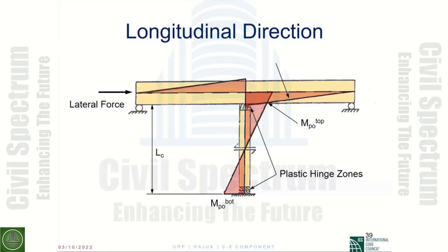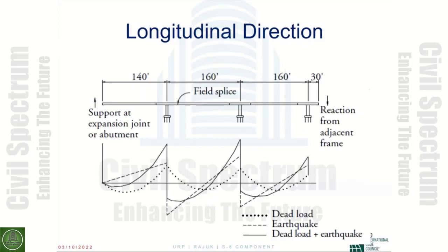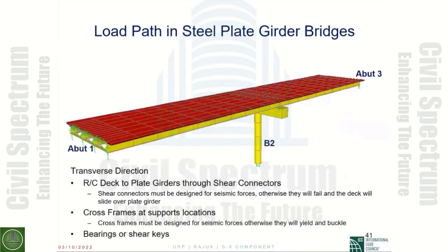Once you do free body diagrams and sketches from basic statics, they become extremely important regardless of whatever the computer program would show you. You need to add these to the earthquake force or subtract them, and that's what you have to pay attention to when you design the superstructure for the seismic load.